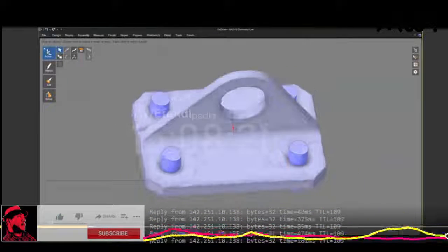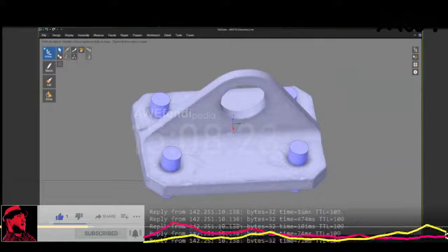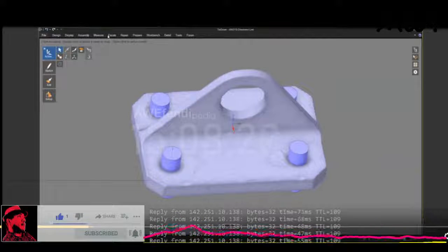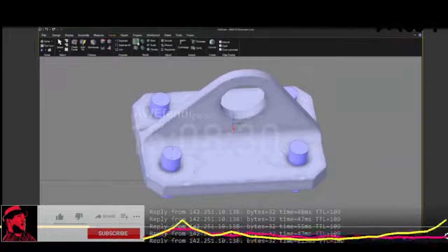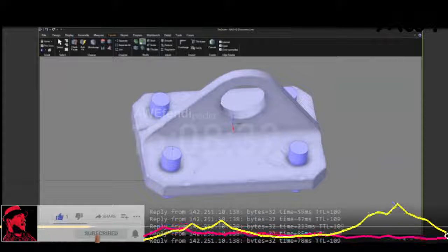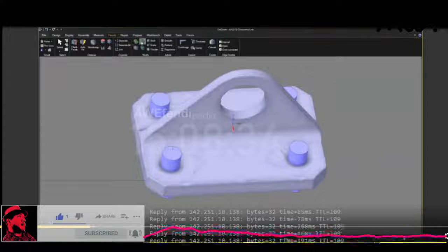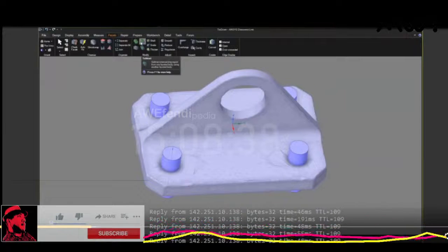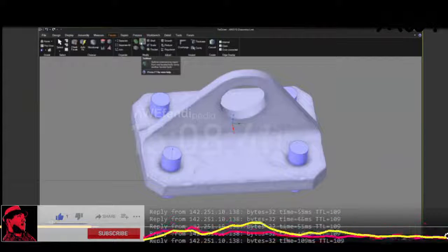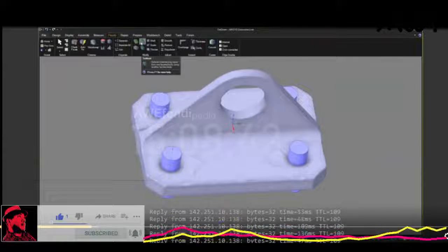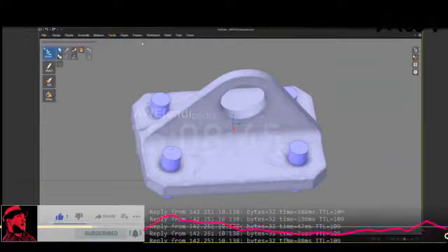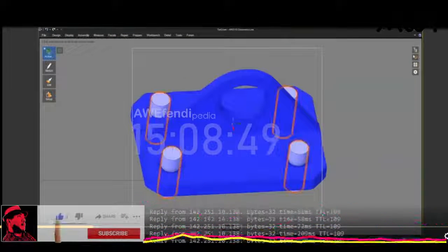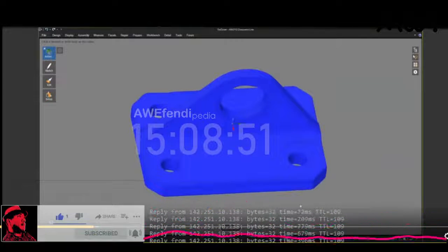So now what do I have here? If I look at what I actually have, BREP CAD geometry along with facets. We can leverage both of those in our environment here. I've got tools that allow me to merge, subtract, split, and I can mix and match as well. So whether it's a facet model, a scan to an STL, BREP, or STEP files, whatever it is, I can use these tool sets to do that. So I'm going to take this bracket and cut out holes using all 4 of these pins. So now I have holes.